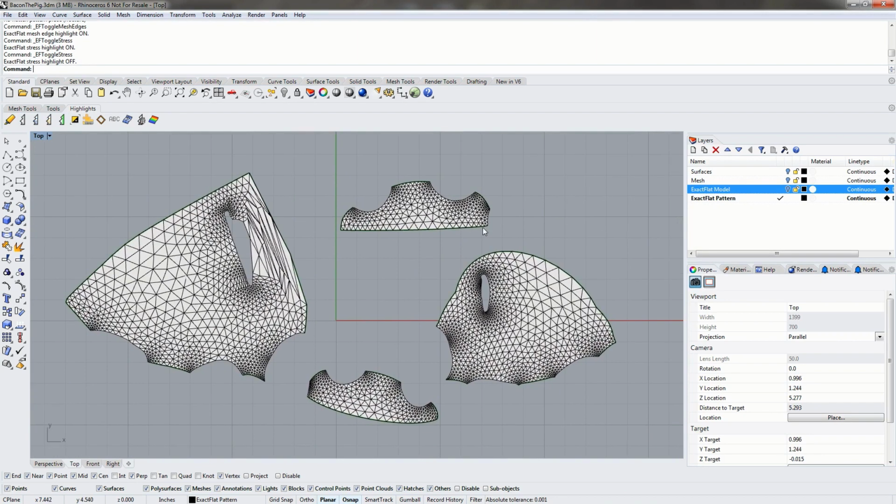So to summarize, there are three main ways to remove folds or wrinkles or flip triangles from your pattern piece. The first method is to simply use a different pre-flattener to create a new initial unoptimized flat pattern. This is probably the most efficient and best method for removing fold or wrinkle. If the shape of your pattern piece is very important and you can't or you don't want to use a pre-flattener, then you can use the automated flip triangle removal tool. It will attempt to remove flip triangles without altering the shape of the pattern piece.